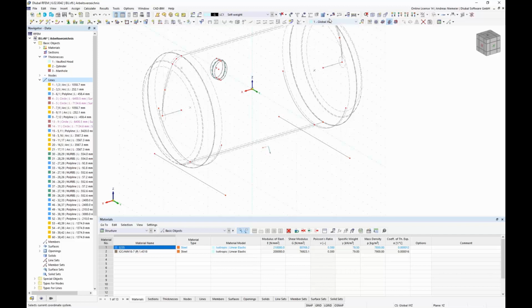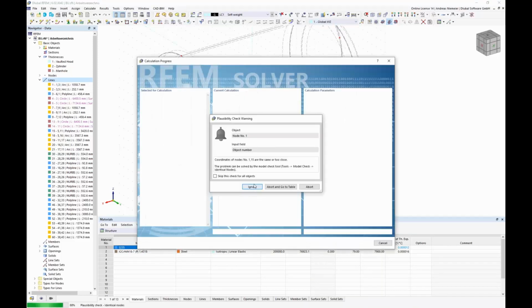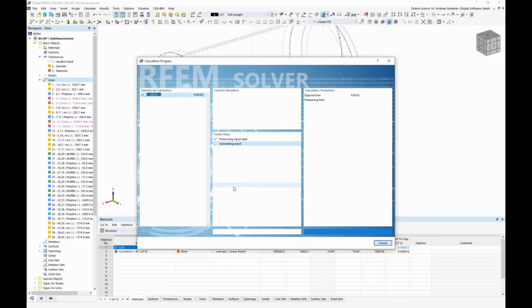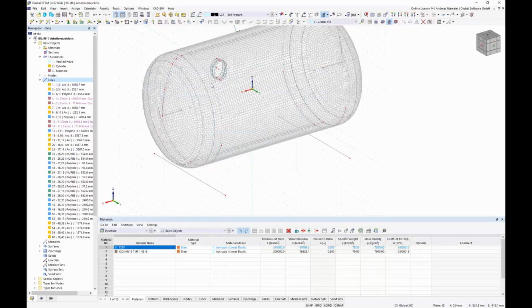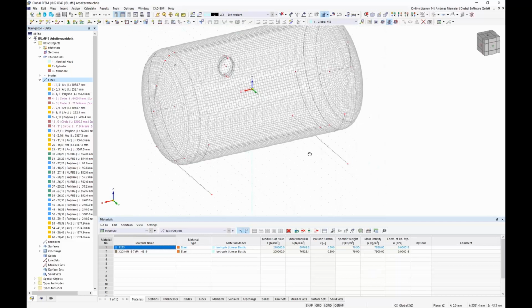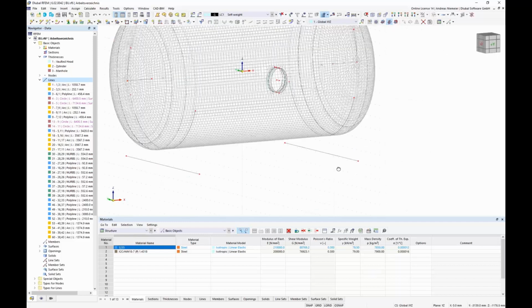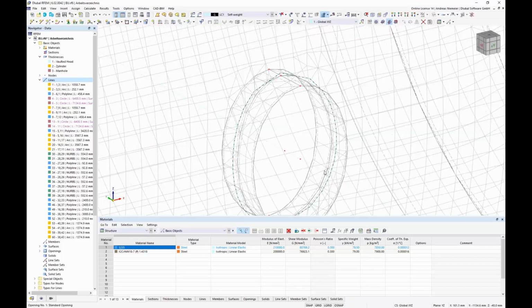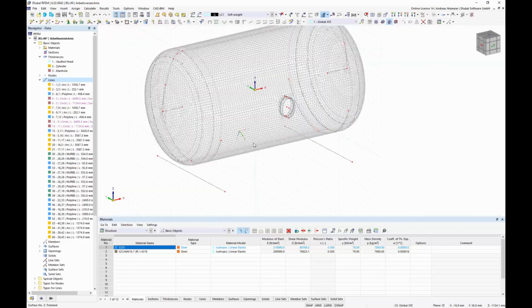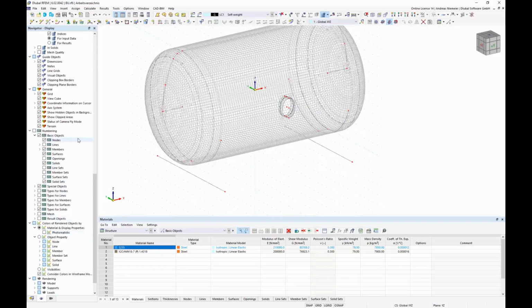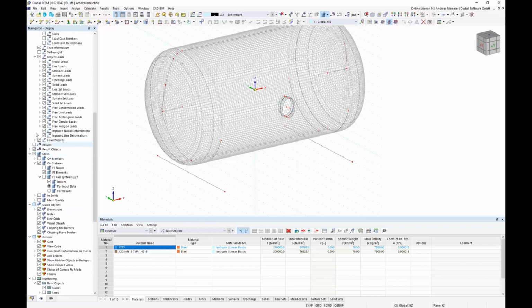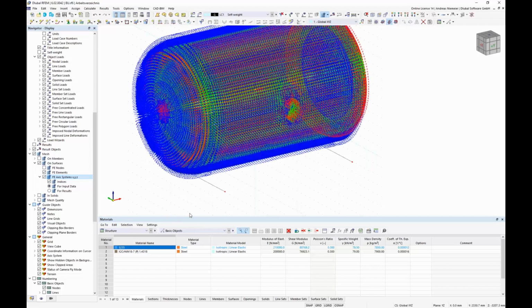And we generate the mesh. And you see, okay, for the global structure, the mesh looks fine. Even this hole is considered, but we are interested in direction and orientation, so we check it here with mesh axis directions, and you see now a forest of coordinate systems.